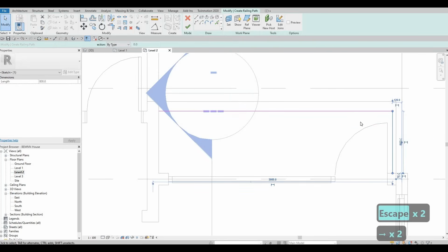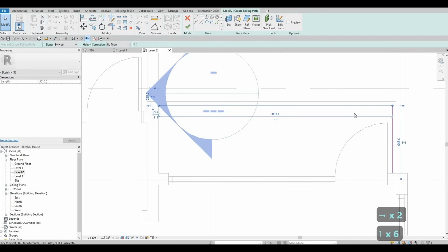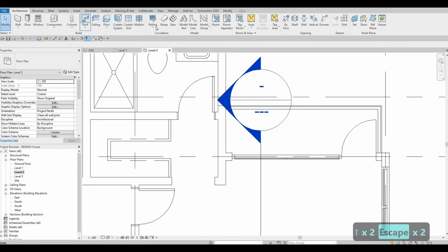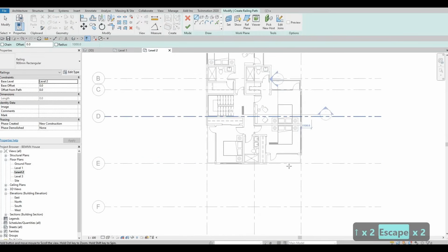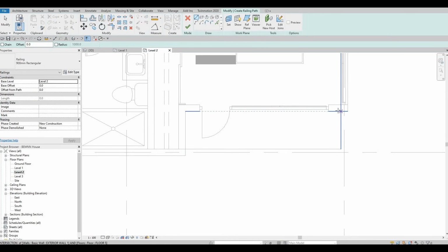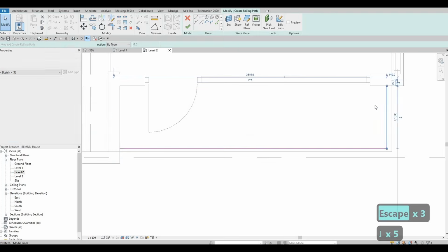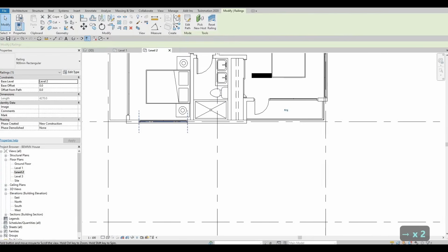You can use your arrow key to select so that you can move it, and then click finish, press escape, and then click railing again. You need to connect it to the wall, and then just like that, and then you can nudge it in place if you want to maximize where you want to place it.